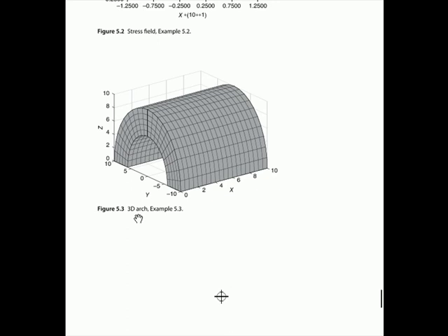Okay, now we're going to do a 3D example, and we have to use a collocation method with PD2D. So it has to be a simple region. Each cross section here is like the arch we just did, but it's three-dimensional. It's a thick airport hangar or something. Can we express this in terms of parameters with constant limits? Yes. We're going to let x just be p1, and so p1 will go from 0 to 10. Then y and z will be expressed in polar coordinates, with r going from 6 to 10 again, and theta going from 0 to pi.